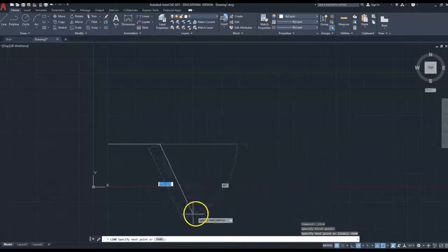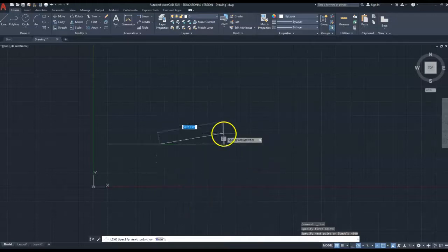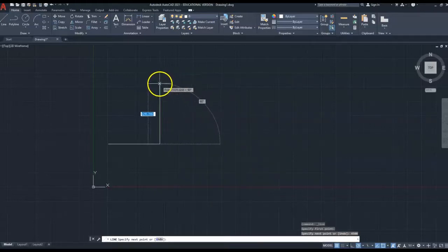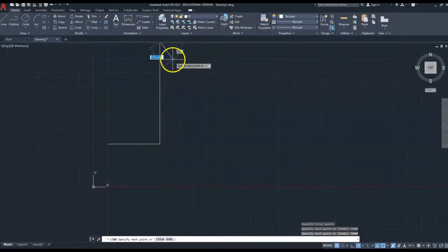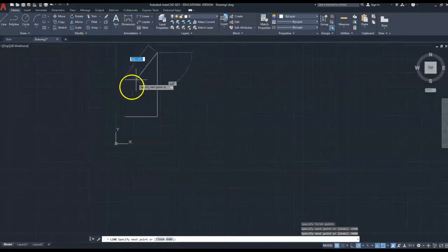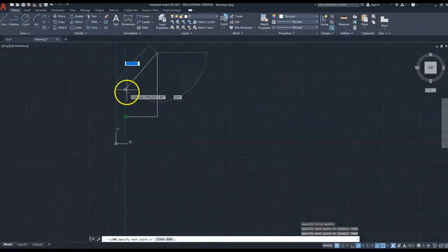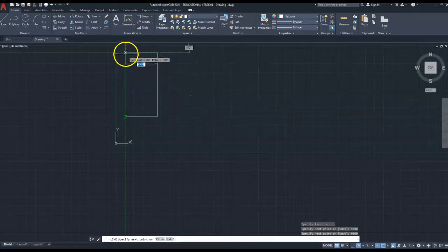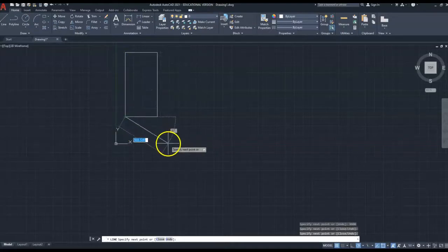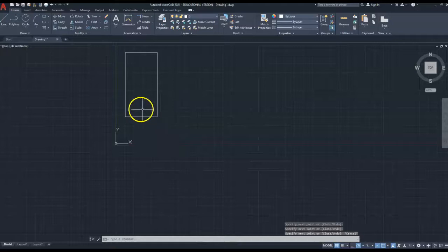And again, as from the previous one, this wants to carry on. Now I could, if I wanted to, because I know that the depth of my house is roughly about 9 meters normally, so that's going to be 9,000. And now, as before, I've gone off the end, so I'm just going to use the wheel on the mouse and zoom out a little bit so I can see. And now I'm more than happy for that 4.5 meters across the back to be the same, and come down there, and that would be the party wall between the two houses. So now I'm going to click escape because I don't want that horrible button on there.